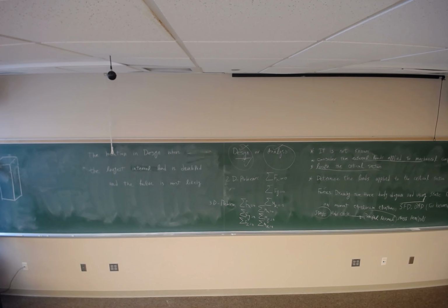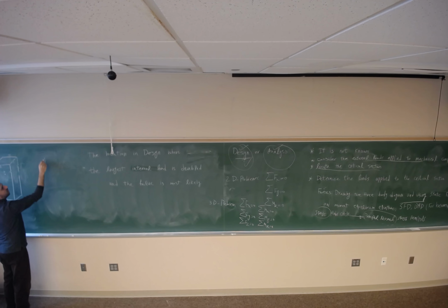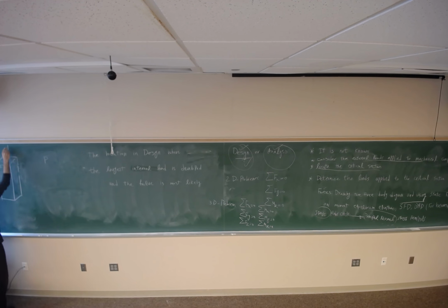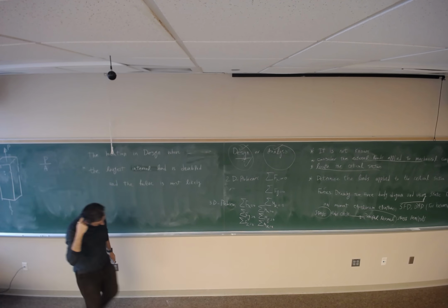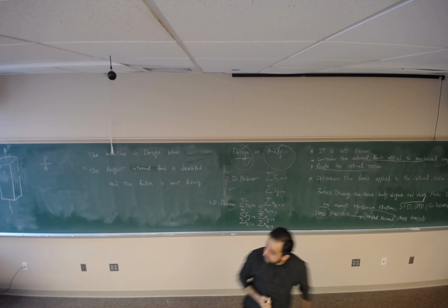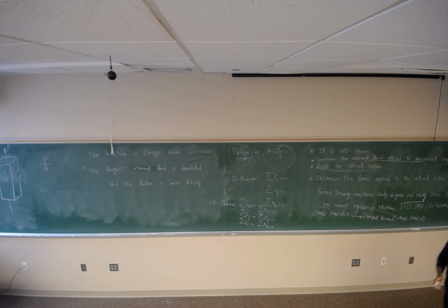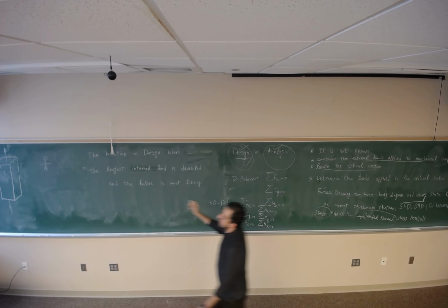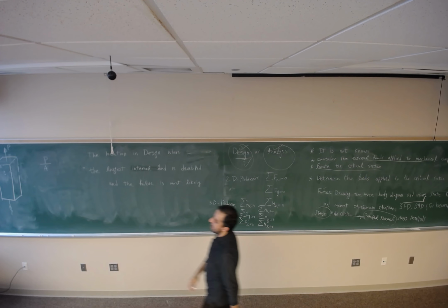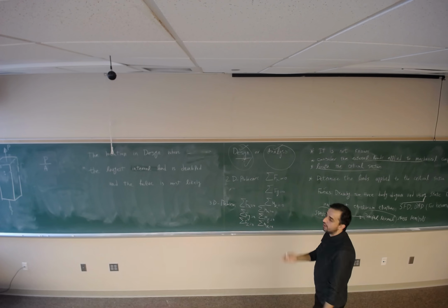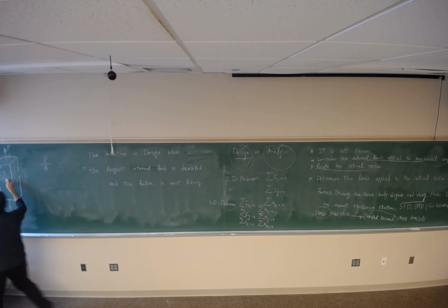So the definition of the stress is force. Suppose it's under an axial load of P. Stress is P divided by A. But it's an incomplete expression if I say the stress at point A is P divided by A, unless I specify which plane point A lies in.